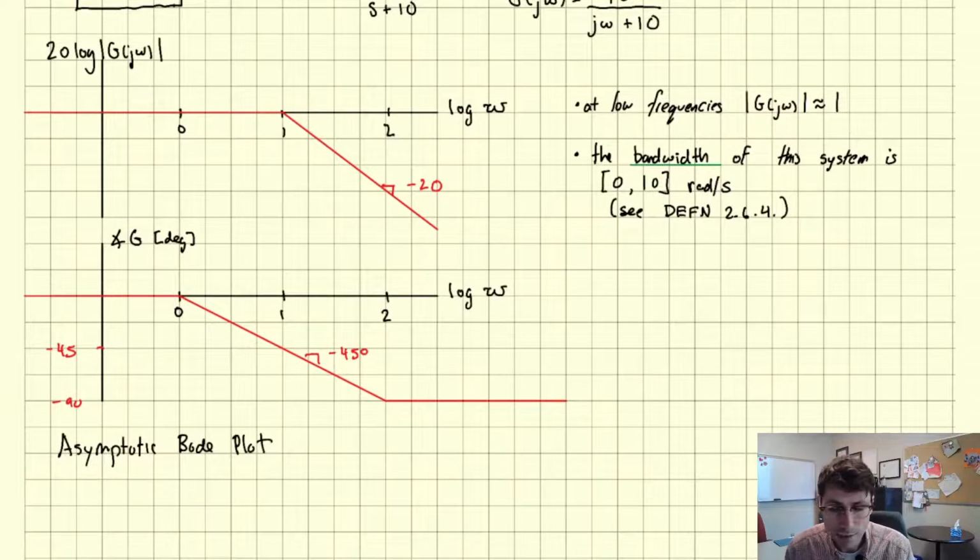The point being, it's easy to read off a Bode plot, right? You just go in for a low pass kind of system like this, you look at the low frequency gain, which in this case is 1, and then you figure out the frequency where it drops 3 dB. And so for our asymptotic Bode plot, that's exactly at the pole location.